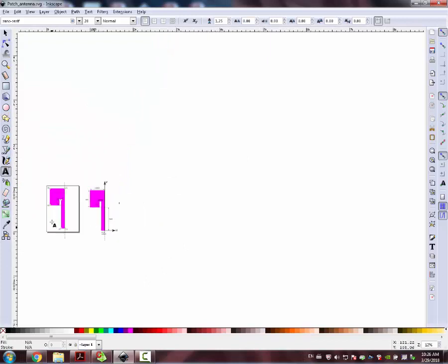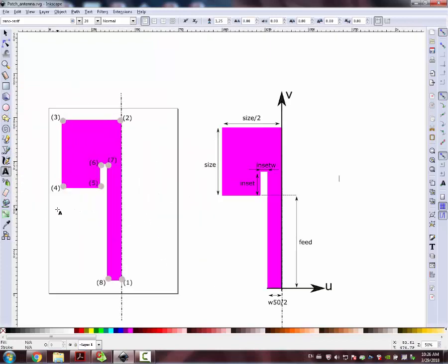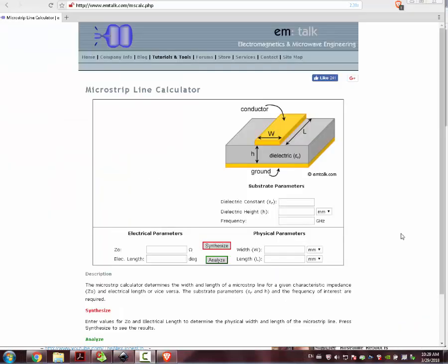So in our procedure to design this inside FEKO, we are going to inform FEKO of all these 8 points. Of course, the 8 points are defined by these dimensions, these variables, as FEKO calls them. Then we design just half of the structure, and using mirror, we design the other half. It's one of the simplest ways to design this structure.